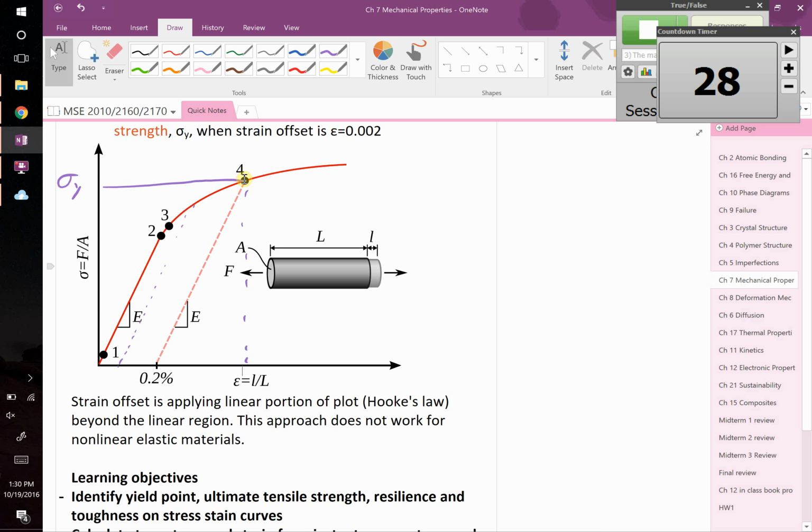Okay. So when you report these, yield stress has to be as a function of conditions, right? So that's why there's ASTMs. It would tell you how long you hold it for, how many times you have to do this maybe, what temperature this happens at. That's why ASTM standards have to exist, because there's all these other variables that could give you, unfortunately, incorrect values. Or just confusing, like multiple values for the same thing. But there's not actually multiple values, there's multiple phenomena happening. There's just different things. Creep or no creep, basically.